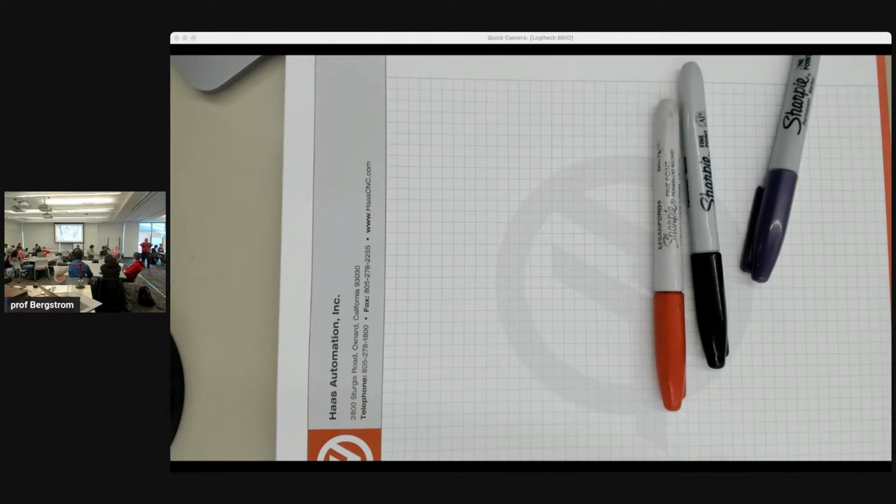So if you set the work offset on the top of the stock material and it says Z 0.1, that's where the tool's trying to get to at the moment of pressing feed hold. When you press feed hold, you look at that line, it says where it's going to. Then you look in the machine and visually estimate how far away it is.